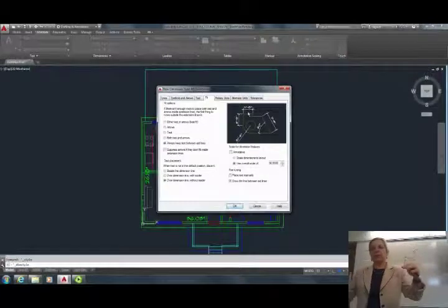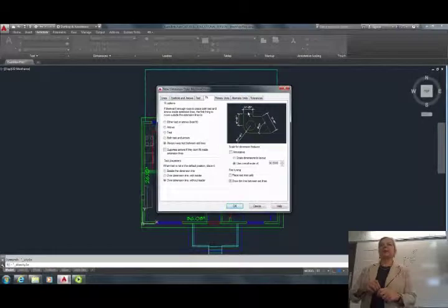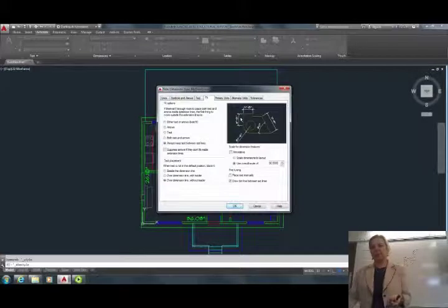And on top of it, if AutoCAD doesn't have room for something, AutoCAD automatically throws things off, and then it has leaders. So there's a number of options for how your dimensions can look. But there's only one look we want for construction drawings, and that means always keep text between these extension lines.